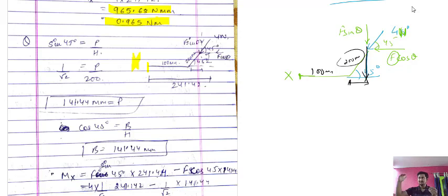Now you can see this force component is above this line of action, so this point is below. Suppose, for example, this was the line and this force was acting here at the same line of action, and we wanted to calculate the moment at x. There will be no effect of this force in producing a moment. Why? Because the force will be there but the perpendicular distance for this point will be 0, because the line of this force is acting here. Moment is produced by force into perpendicular distance, but there is no perpendicular distance in this case.